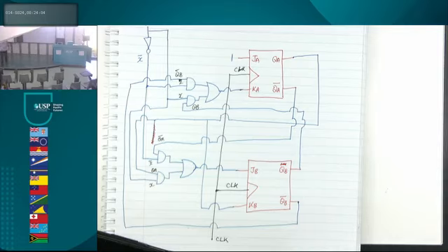You'll connect an LED to QA and connect an LED to QB. And then in that cycle, there's an X over there as well. When X is equal to 0, it will go A, B, C cycle, like what we've drawn in the question. What is it, 0, 1, 3 or something? Or 0, 3, 1. And when X is equal to 1, it will go the other way, right? So it will flip. The lights will go 0, 0, 0, 1, 1, 0. It will light on, double off, 1 on, 1 off.